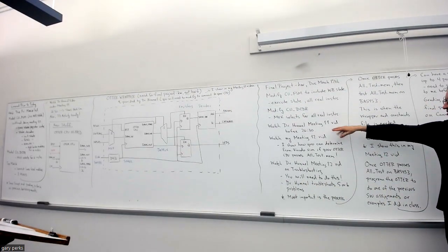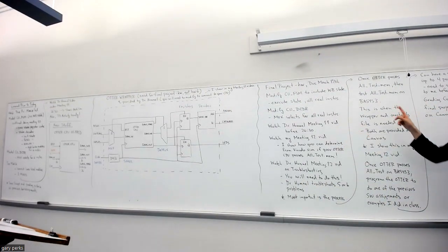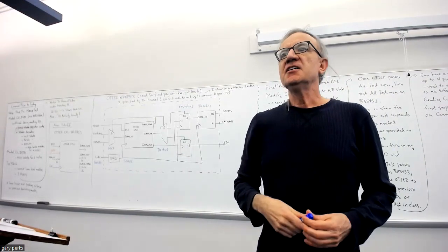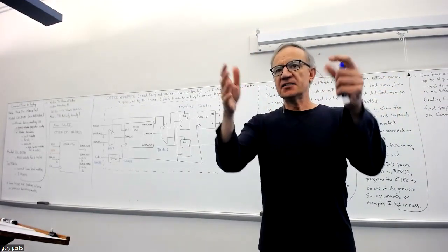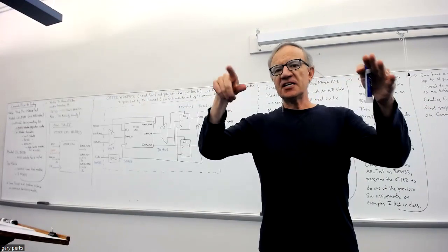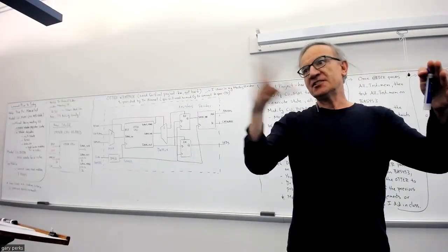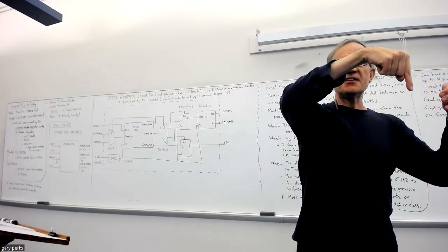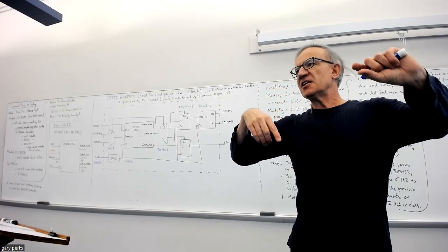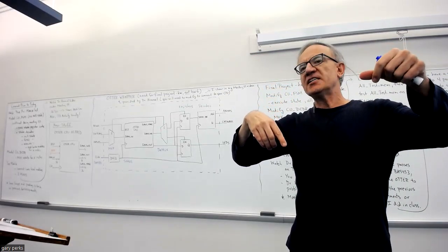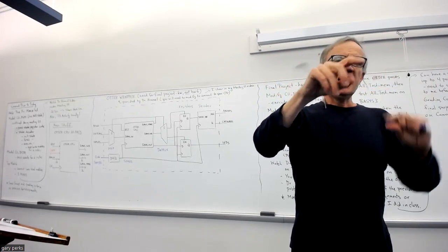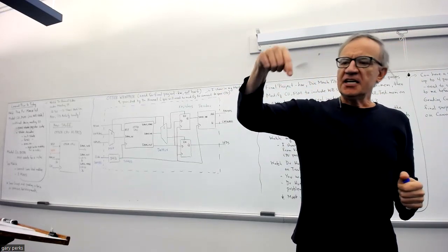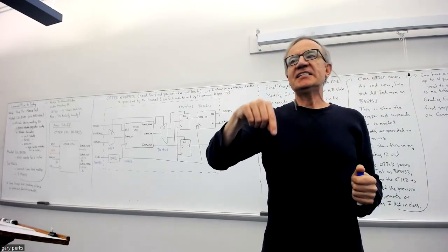In my video, in this Meeting 12 video, I show you what it should look like on your Basys board when it's working correctly. What you'll see in the video is that on your Basys board, when it's running that all test mem file, where it's checking the thirty-some odd real instructions, you'll see the LEDs lighting up right to left. And then you'll see the 7-segment display increment by 1 in hex. We'll start at 0, and you'll see the LEDs flash, and it'll go to 1, LEDs flash, 2, LEDs flash, 3, and so on. Each time an LED flashes, it's doing a test.